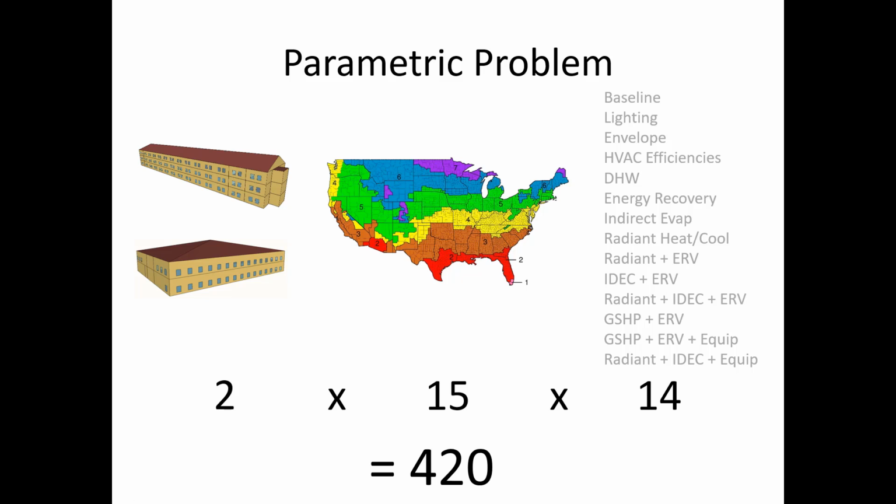This video will demonstrate how to quickly change the design day parameters within an Energy Plus model such that it can be simulated across multiple different climate zones. So this gets back to our parametric problem, which we showed in the second video.